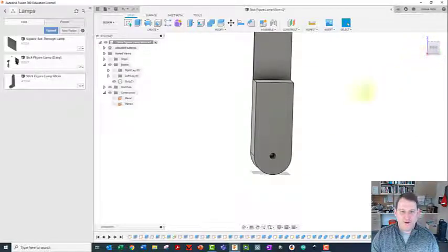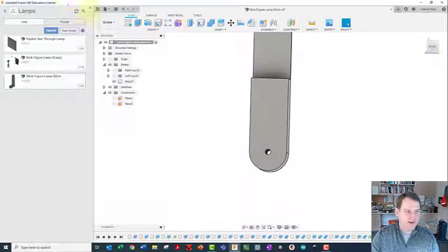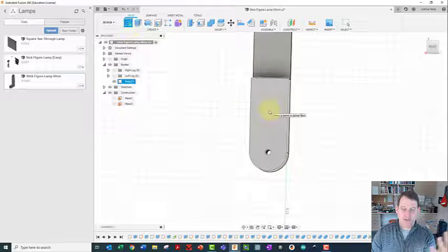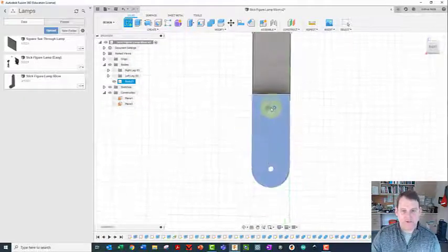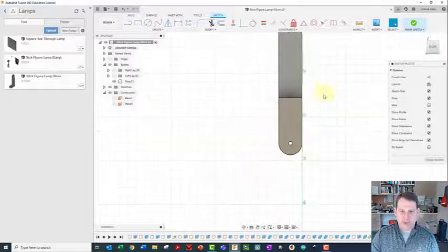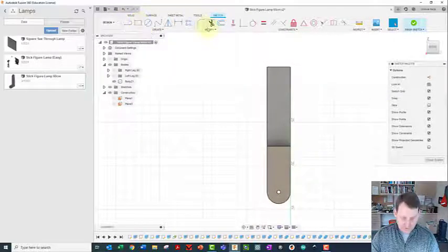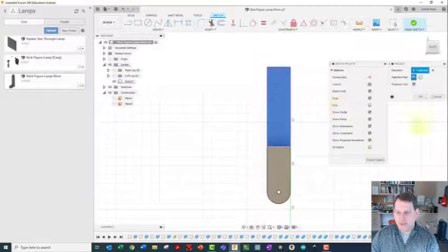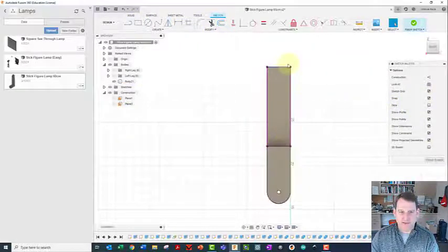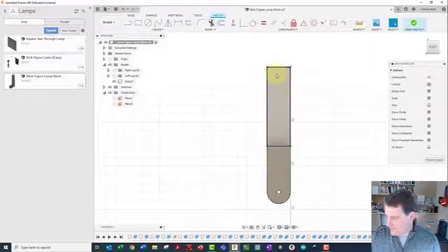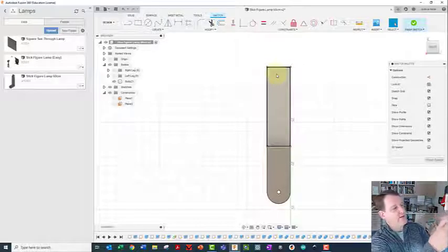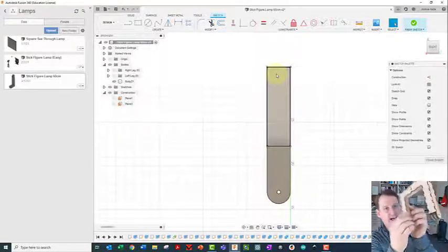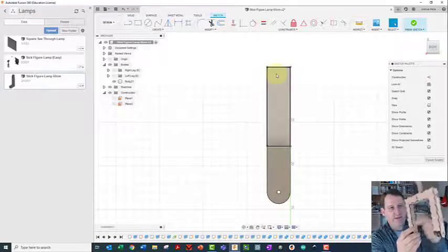All right. Now, once again, we're just going to do the outside edge, right? So we did the outside edge, now we do the inside of the leg. So I'm going to click on this, create a sketch here. That's already got that piece. So now I'm going to just project this back square onto here. So now that's the exact same length, except that outside length goes all the way to the top here. Well, we want this inside leg right in through here. This is the inside piece we're making right now.